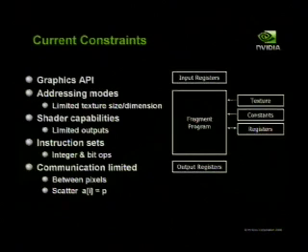One other area is that this tends to be a very communication limited architecture. Pixels, or these fragment shaders, are not allowed to talk to their neighbors. Typically, our graphics hardware is actually working on multiple pixels at the same time. It wouldn't make sense to have one extremely fast shader doing one pixel at a time. We'd have to run that at an extreme clock rate in order to get our times down. So what graphics architectures do is they actually stamp out multiple of these fragment processing units to work on multiple pixels in parallel.